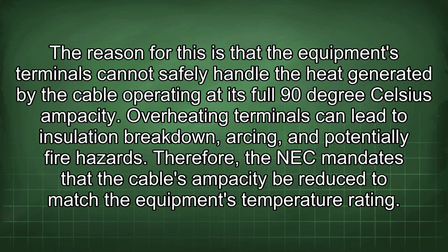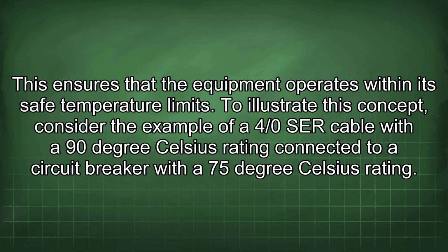Overheating terminals can lead to insulation breakdown, arcing, and potentially fire hazards. Therefore, the NEC mandates that the cable's ampacity be reduced to match the equipment's temperature rating. This ensures that the equipment operates within its safe temperature limits.